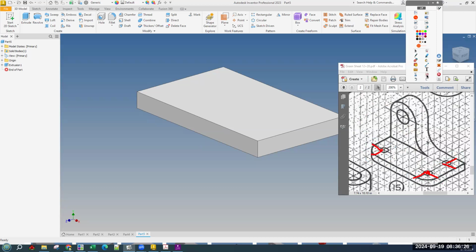But what's nice is if we do the fillet first, when we go to make the sketch on this to draw the circles, the sketch will take the fillet and give us a center point, which is actually the center point for the hole. Same thing on this side.